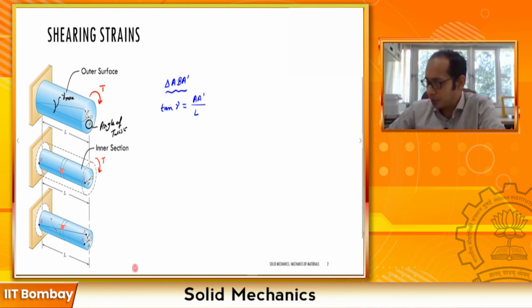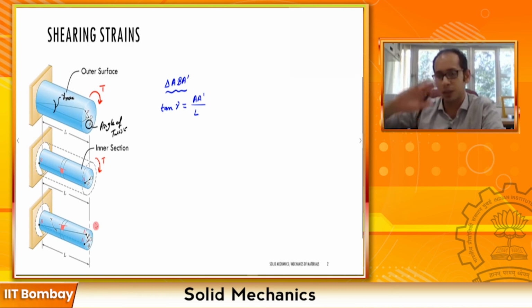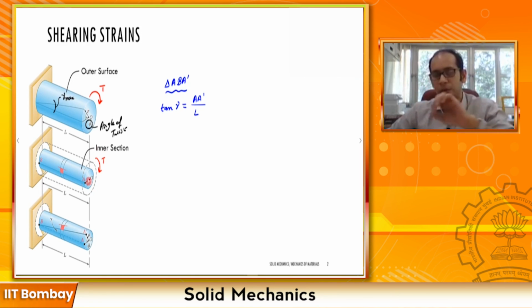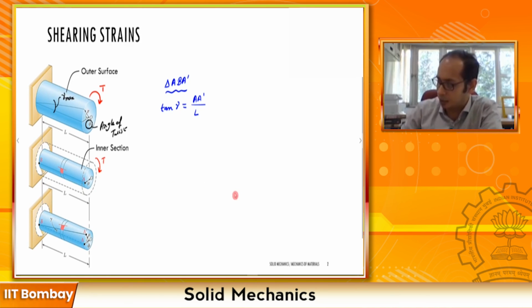Now, for this same arc, this A prime, which is inscribed in this cross section over there, if I try to relate it with this angle phi, remember the outer radius here, as is shown, is R, and wherever on the inside I'm taking the cross section, if I call the inner radius at any particular subsection of the shaft rho over here, for this shifting of the point from A to A prime, I can also write A prime as equal to rho times phi over here, right?